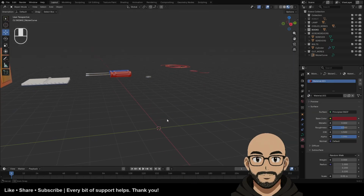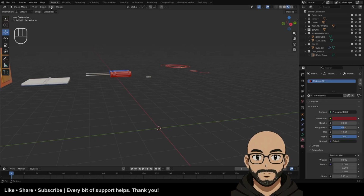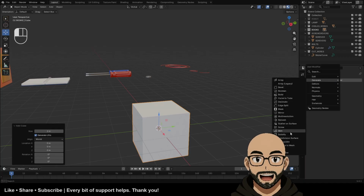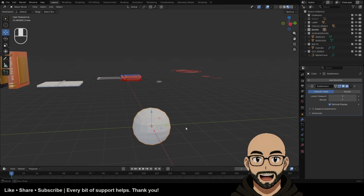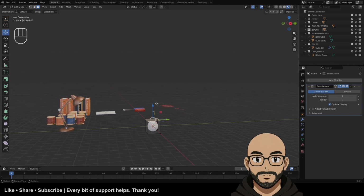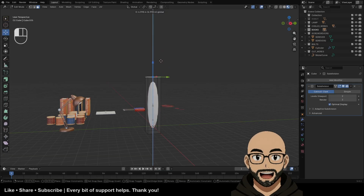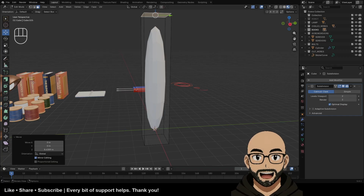Let's build a pencil. Pencil's going to be really easy. Let's start with a cube. You wouldn't expect to use a cube for a pencil, but I'm going to use a cube. And we're going to just add a subdivision surface. Boom. Alright, increase that count. What I'm going to do is select that top face. I'm going to pull this up, like so. About that high, it's fine. We're not going for a fully detailed pencil.